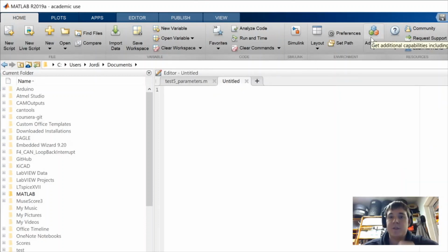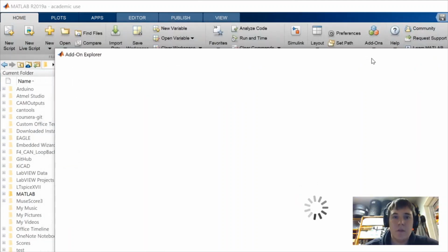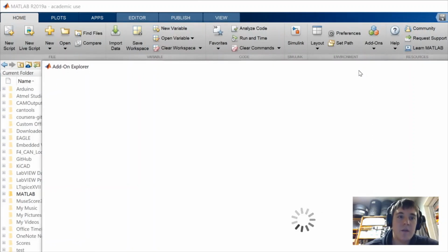We also need to install all the packages that are needed for the code generation with Simulink, which is several files. To begin with, we need Simulink. We also need the Simulink and MATLAB embedded coder.